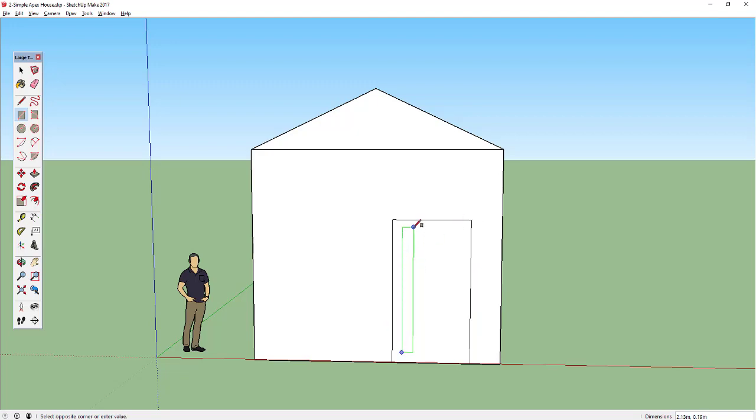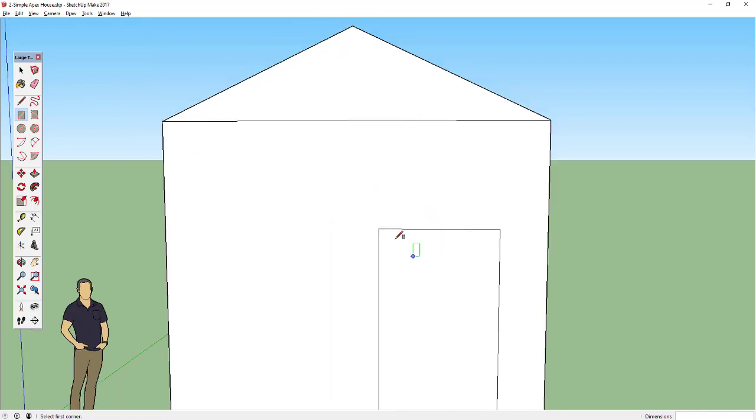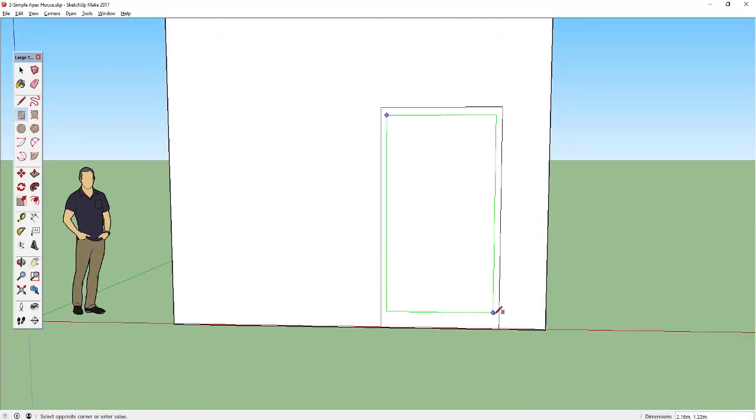Okay, draw a frame just to make it a little bit more interesting. And then what I'm going to do is draw an arc just above. So it's A for arc, and it requires 3 clicks. I'm going to draw that one again, but then really look well. So Control Z, undo it, just to make a frame.